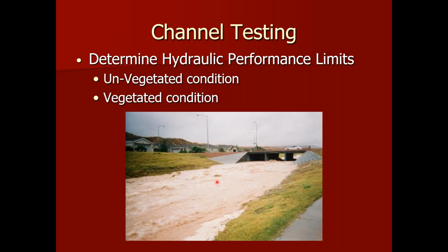It is how we test these systems, however, so that we ensure that the performance values we get in high energy conditions are certainly able to be interpolated down to lower energy subcritical conditions. Going the other way, we know from a lot of work that's been done in energy dissipation that testing in a subcritical application and applying to a high energy supercritical application is not at all conservative.